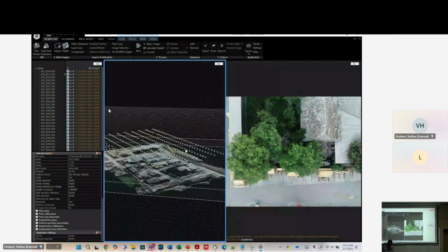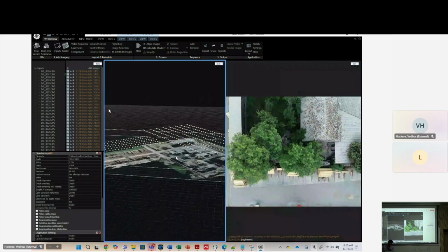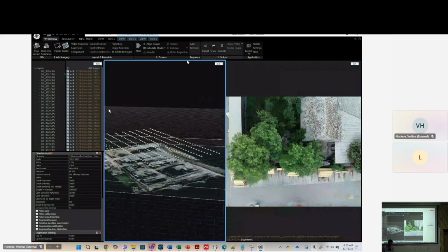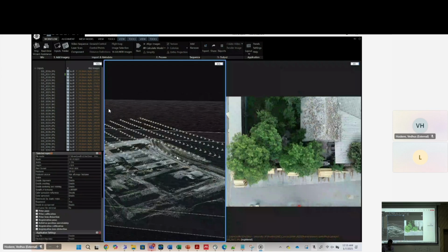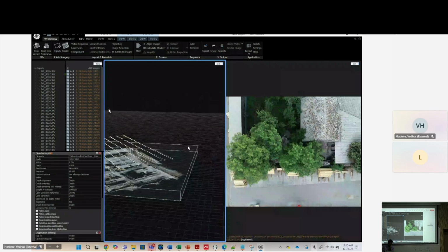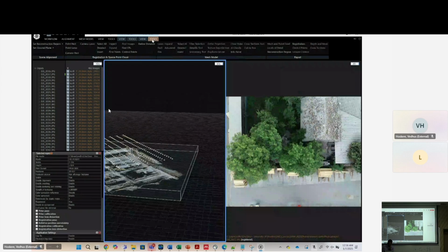So if you're happy with this, then the next step is to just densify. But if you want to make some changes at this stage, say there are some parts that you're not interested in, you can change the scan volume, right? The volume can be changed. You can also make some edits after you do the reconstruction.